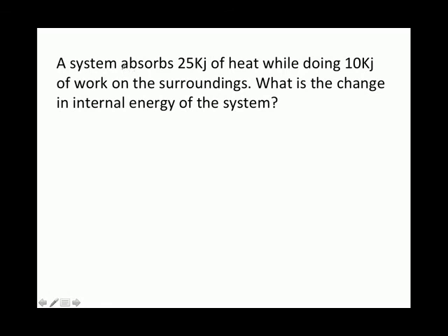So here, absorbs is the key word: it absorbs this much heat. And then it's doing this much work. So that means the internal energy of the system is going to increase by 25 kilojoules, and then decrease by 10 because it's doing some work. So here's our formula. We plug in our numbers, and we wind up getting a difference of 15 kilojoules. So overall, the internal energy of the system has increased by 15 kilojoules.